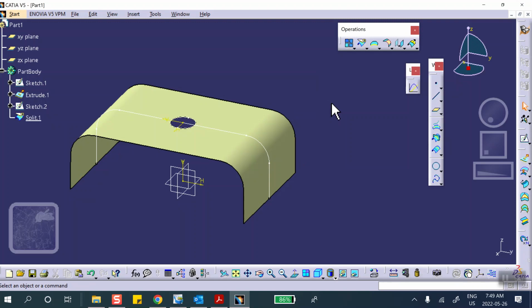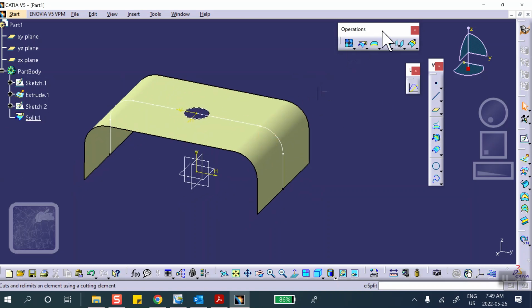The way I have done it does not require a join. Okay, we're talking about shells now. The way I've done it does not require a joint, and it's already, think about it as a single surface. So when I mesh it, the entire thing is going to get meshed later on, and the material property, when I apply it, is going to be applied everywhere, and the thickness, okay? But just bear with me for a second.